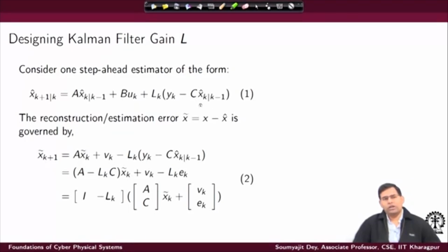I have two sets of equations, right, because I have this equation which is trying to kind of model the evolution of the state estimate, and as you can see, this idea of Kalman filter gain is coming as a multiplication factor or the gain corresponding to the residual, because this is my original measurement and this is my estimated measurement, and that gives me the residual, and I am using this to be handled by the filter here, and the rest of the dynamics is here, or that was there originally, and with this I am generating the estimate, right.